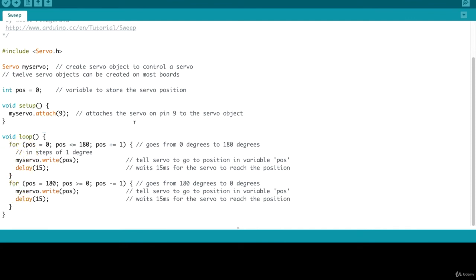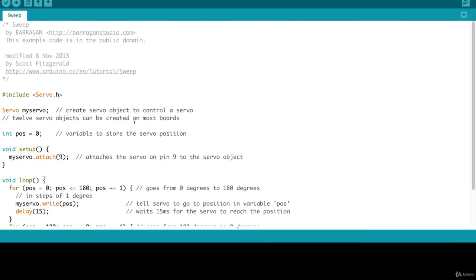So to summarize, for the structure of an Arduino program, at the beginning, typically you'll see some comments. That's followed by includes, where we include our libraries that we might be using. This is followed by variable declarations for those variables that we'll be using throughout our project. Then comes the setup function, where we initially set up those variables and prep our program to begin.